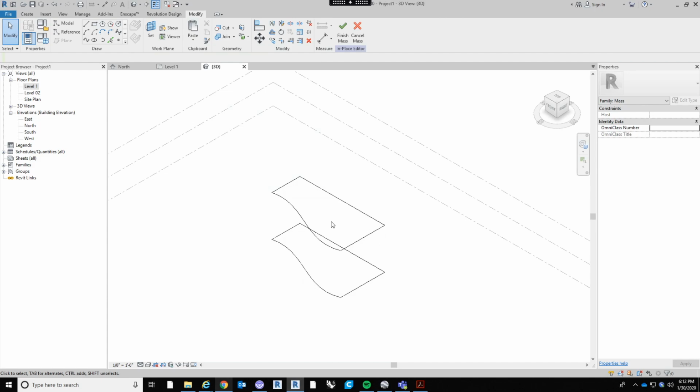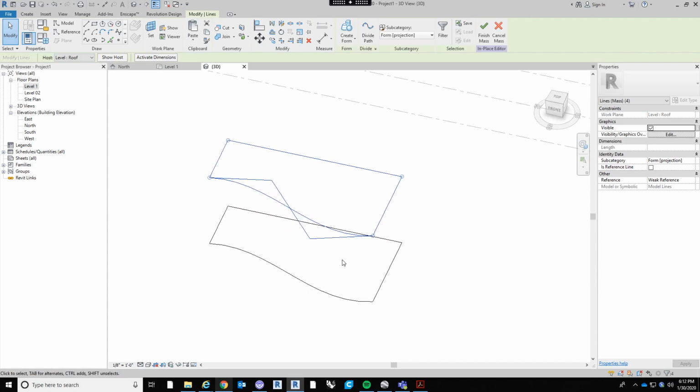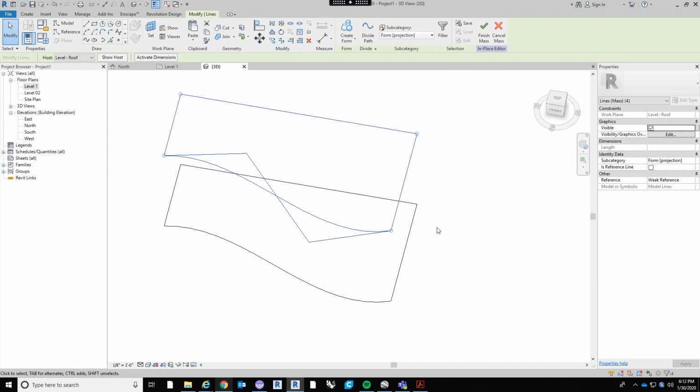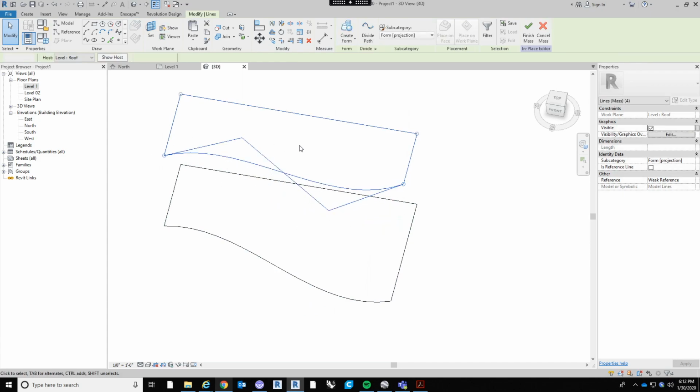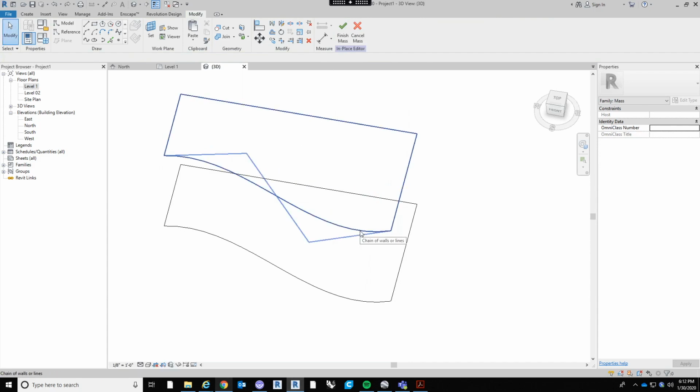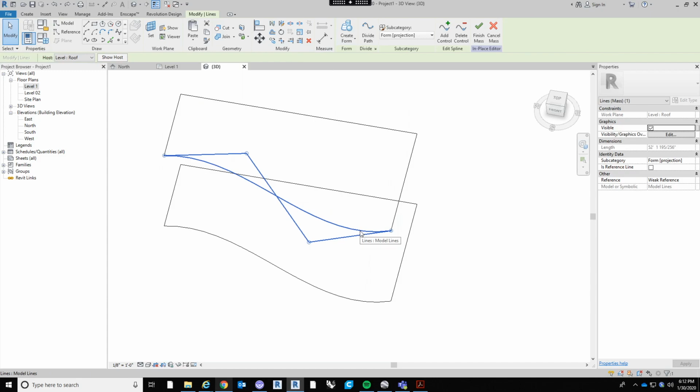Everybody on here? All right. So, one thing we want to do to make this a true double curved wall. So we're going to be creating a mass from these two control points. We're essentially going to loft them together. So what we can do is manipulate, actually, whoops. Let's tab through and delete this one double curve.